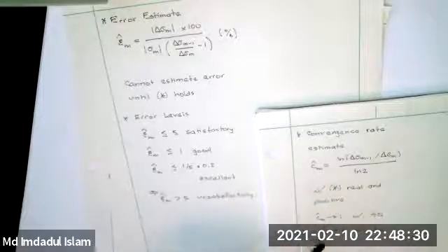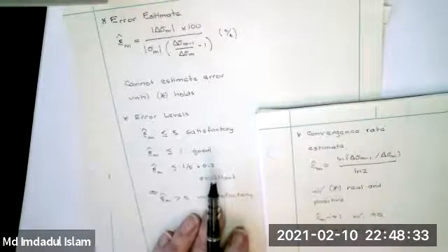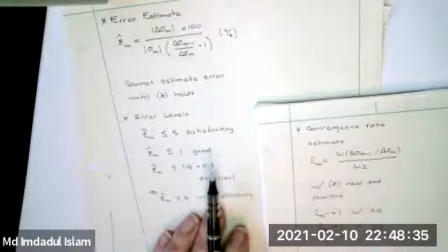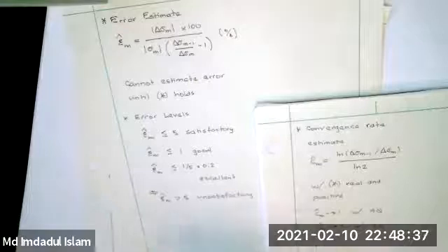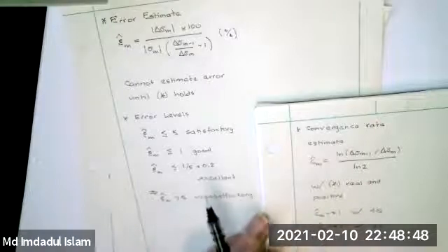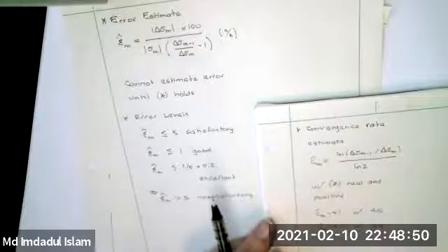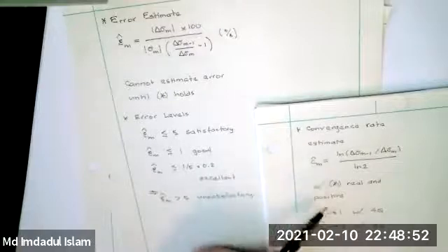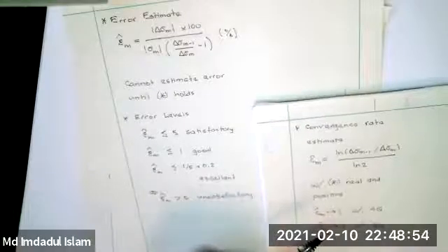On the other hand, for the 8-node quadrilaterals, you can get both constant values for the stresses and linear values. So the thing that's missing there is the quadratic term. Now, this is generally true. Sometimes these stresses don't have a power series, so you shouldn't count on this being true, but more often than not they do. And so you can sort of see this. And if this is not happening, that should raise some questions. And so calculating this is not an unreasonable thing to ask you to do.